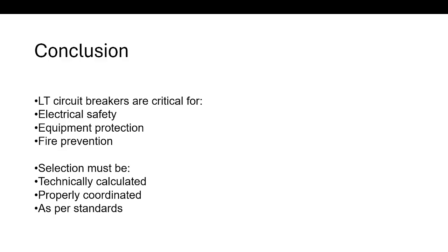Technically calculated means that the current setting must be made according to the equipment you're using, not too high or too low. Too low will cause the nuisance of multiple tripping, and too high will not allow it to trip in case of overload. So it should be used with precise calculation.